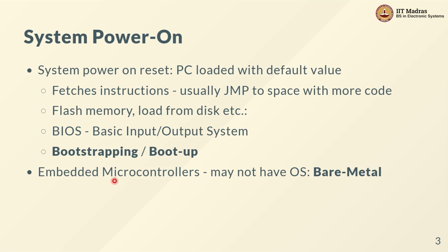The program is getting loaded into a portion of memory that will respond corresponding to what happens when you get out of reset. Which means that when I power on the microcontroller and take it out of reset, it's going to start executing those instructions. Which is perfect because this is essentially what's called bare metal execution, right? I have a processor, I have a small PCB built around it, I have some memory.